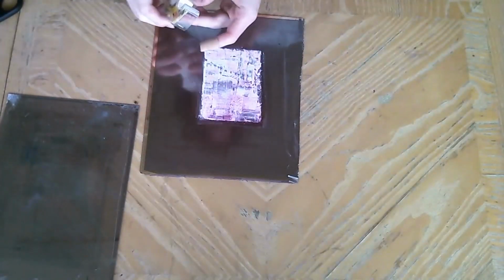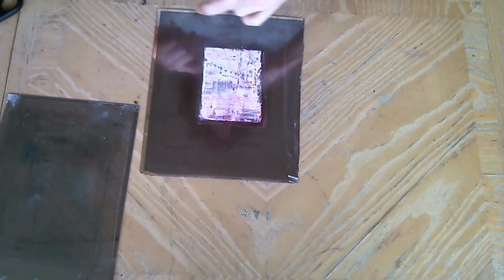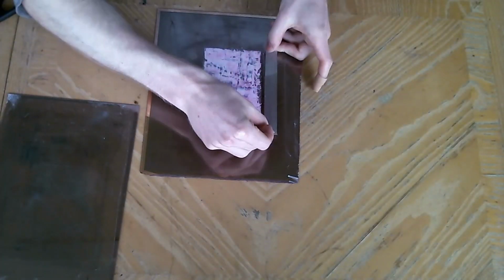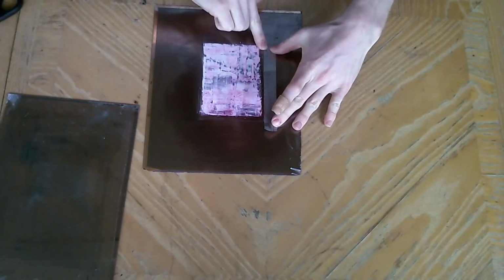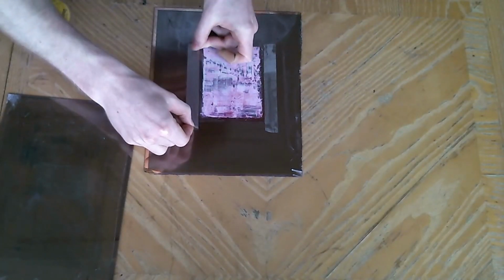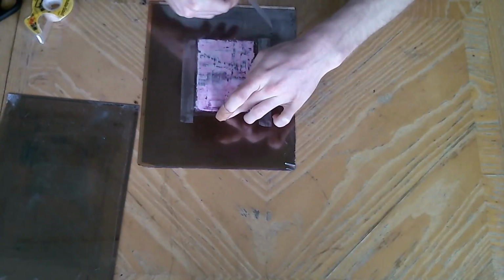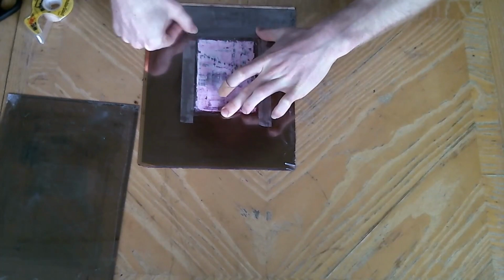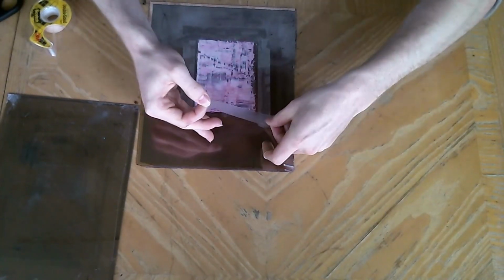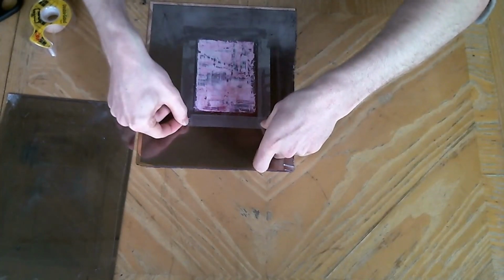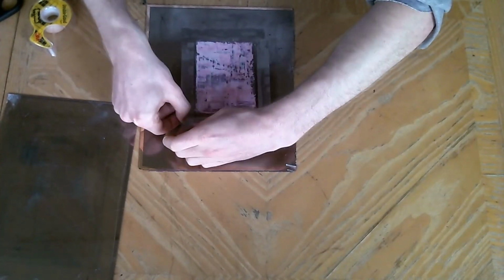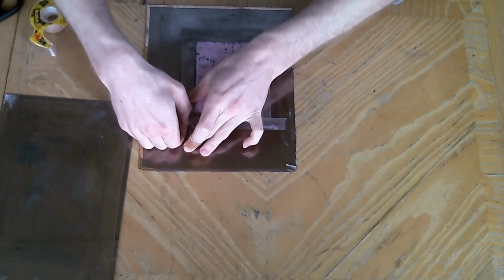In this next step, I'm going to use double-sided tape to create a perimeter around the dyed and sintered titanium in order to adhere the two panels together and also prevent them from touching one another or the electrolyte solution from escaping. The reason we don't want these panels touching each other is because if the two layers of conductive glass are in contact, that will complete the circuit, and we won't be able to capture the energy created by this process.